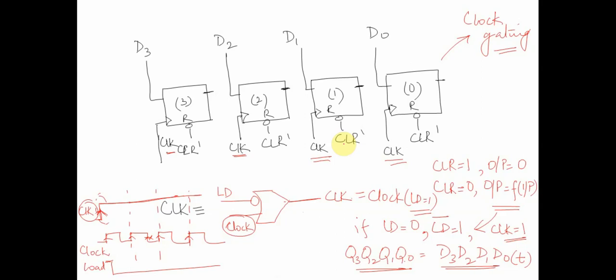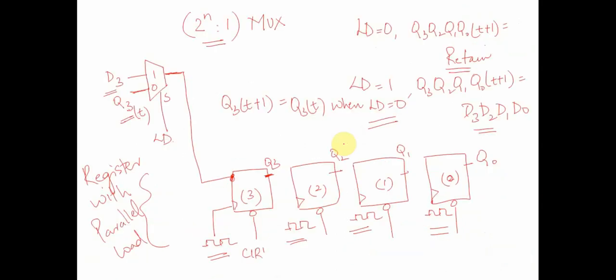Depending upon the value of load, the clock will either toggle or not, but playing around with clocks is usually not at all suggested, because there are multiple other things which a clock might drive in the circuit. So we looked at a parallel approach, a parallel load, where depending upon the load signal, since our output should vary, we implemented a mux, and that mux solved our purpose. And similar muxes would be captured over here also.